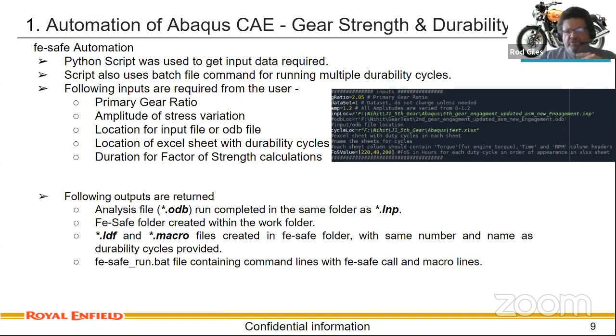process. We are using a script written in Python that generates the LDF that's required for the FE-Safe, and then FE-Safe can run in an automated fashion to produce an ODB which contains the durability data.